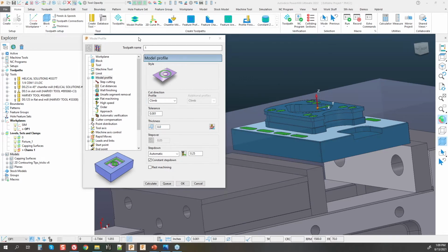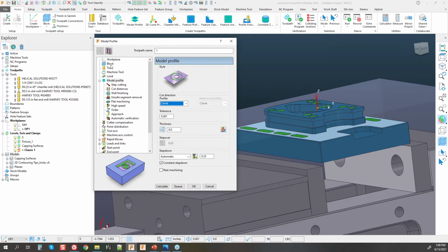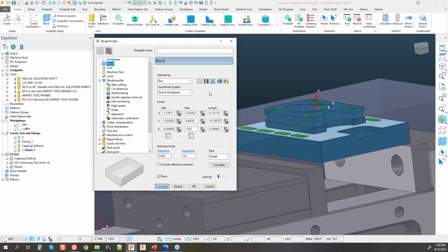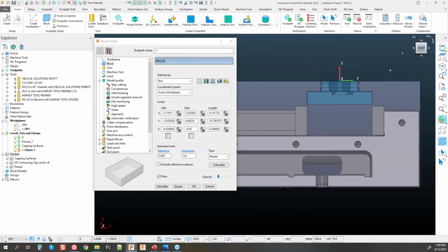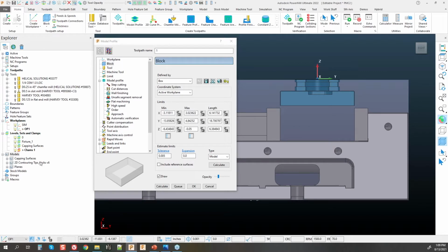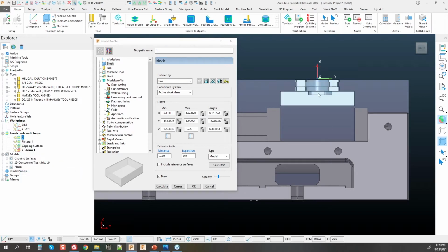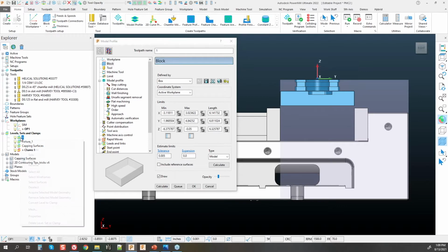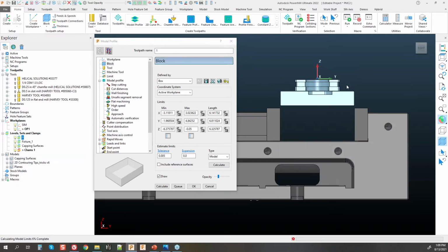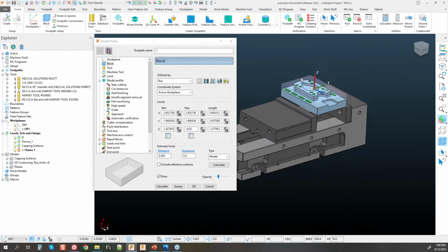So when we look at settings to set this type of toolpath up, block is one of the tool sets that is incredibly important with all of our 3D toolpaths. That's something that we do teach within our classes. I'm going to go to right view for this real fast, and select my part. Actually, I could select that from my levels here. I have a quick key, so I can come in and shrink wrap a quick block around just my part.